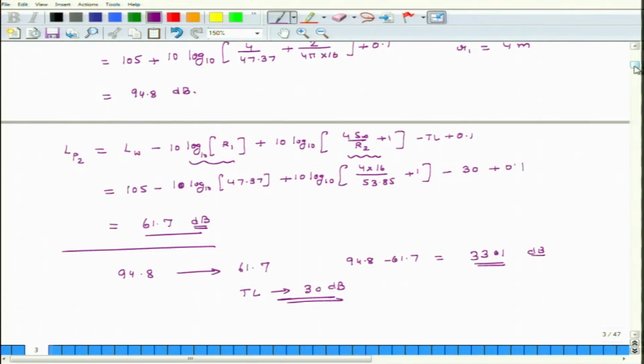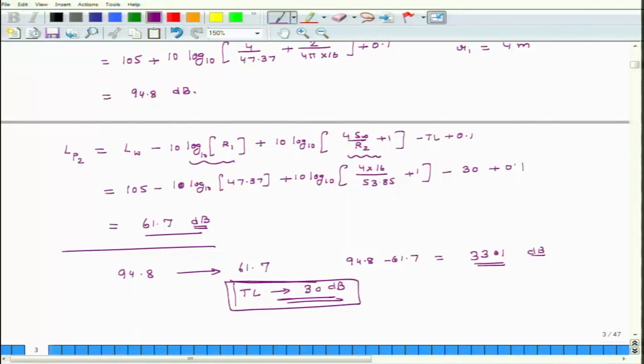So, the point I am trying to make is that the room constant helps make things better, but if you have a partition in the wall, the thicker the wall is and the more rigid and robust the wall is, that is going to be the predominant factor which can really reduce your sound pressure level in the operator room or the adjacent room.